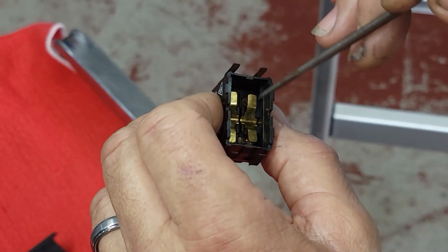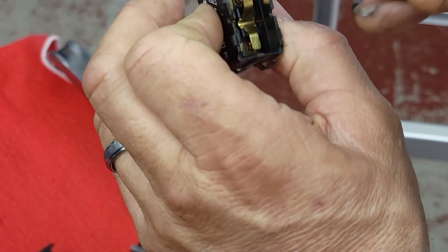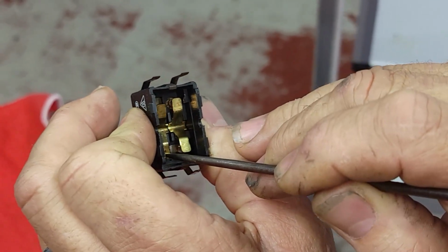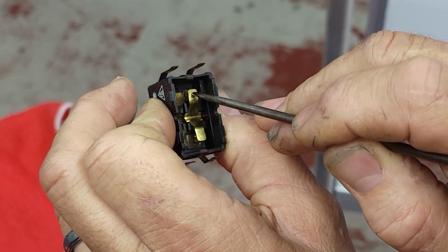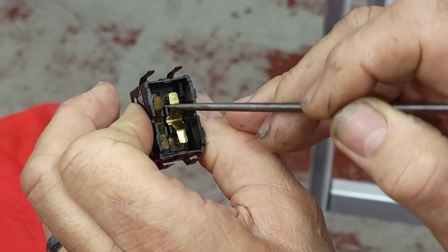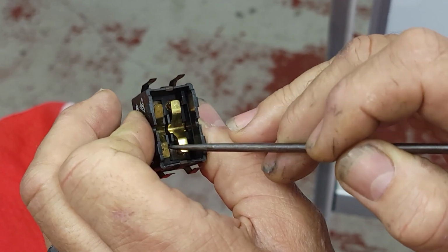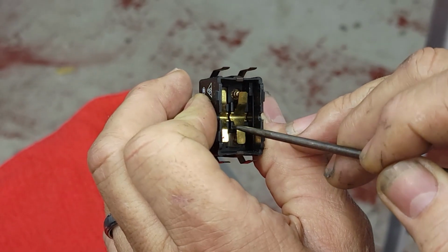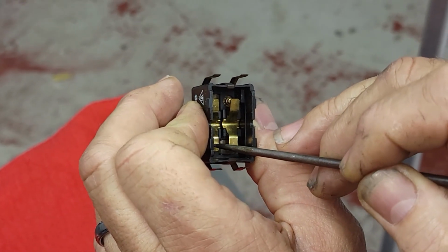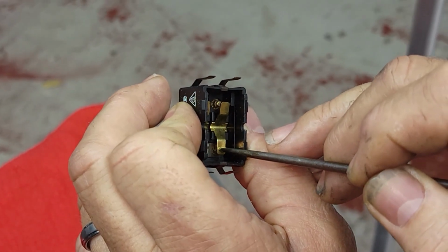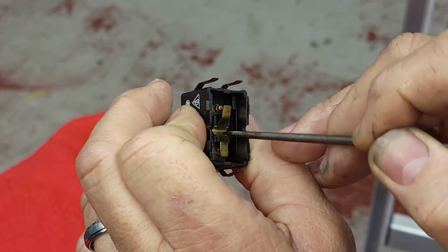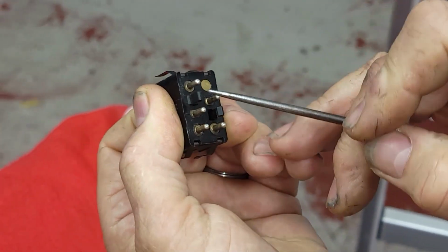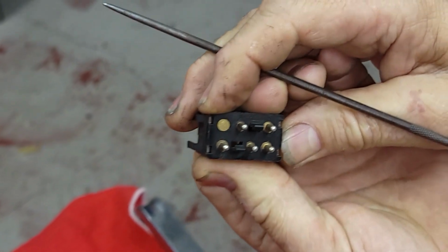Okay, so if you look, when the window switch is in the neutral state, this one doesn't move. This one is touching this terminal. This one is touching that terminal. When I rock the switch up, this one can rock, disconnecting this terminal, but this one doesn't move, it stays there. And same in the opposite direction. This one will go to that terminal, but this one stays the same. So this one stays in its neutral state, and that's pin 1 connected to pin 4. You can see the numbers back there.